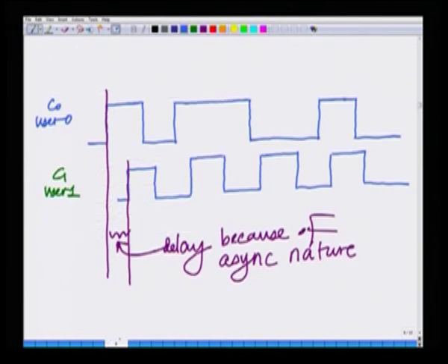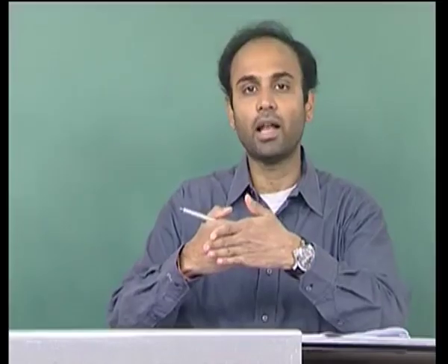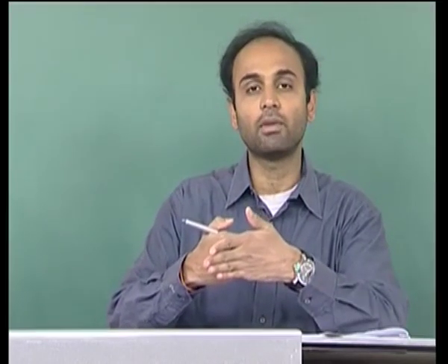Let me go back to the diagram. Let us call this delay a fraction f, assuming that the total chip time is unity, is 1. This delay is a fraction f of the chip time. Now, if f equals 1, then this moves by 1 complete chip, hence again they are chip aligned. So, R01 again becomes synchronous.